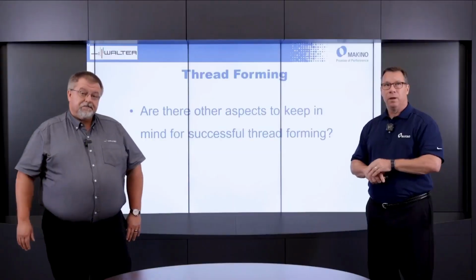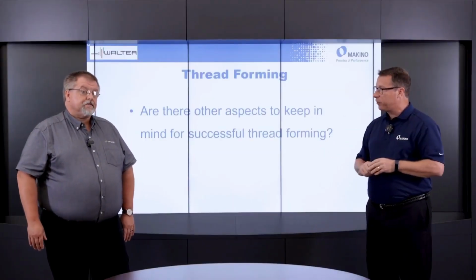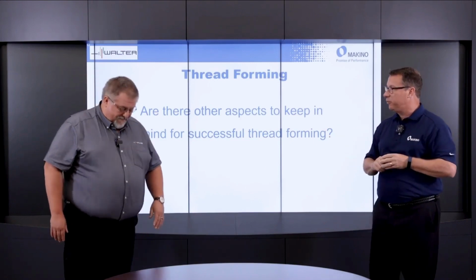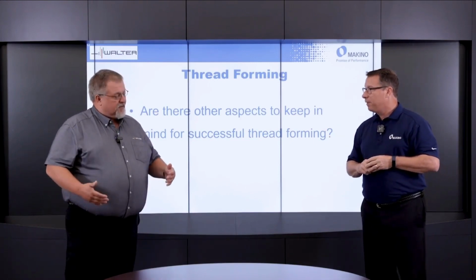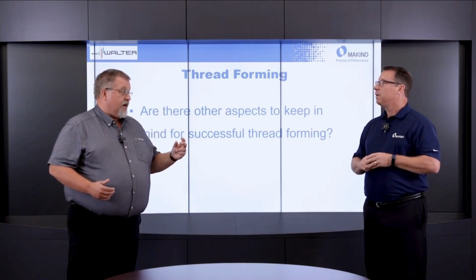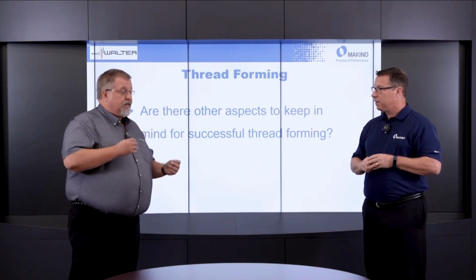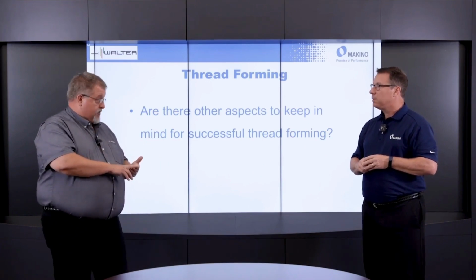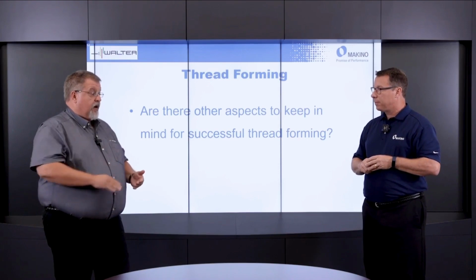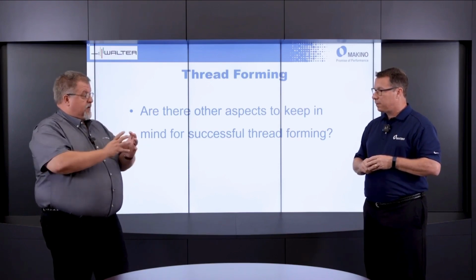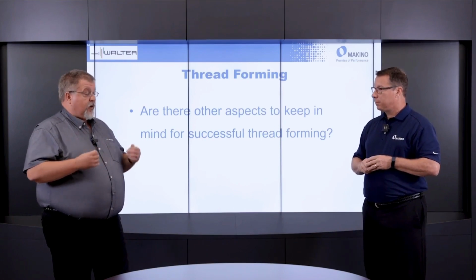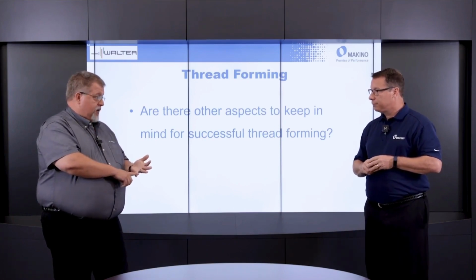Very good. Are there any other aspects to keep in mind, Brian, to get successful applications using thread forming? Yes, there is. One of the most important things is the hole size. You would need to use a different core hole or tap drill for a thread former than what we use for any other process out there. We are forming and pushing this material around. We need to use a larger drill for these. So you've got to make sure you use the right tap drill.